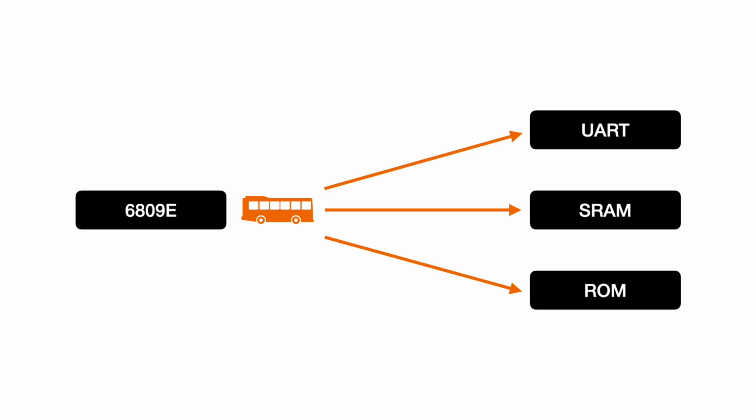Now, obviously, because I'm going to be building a circuit to match address bit patterns, I will need to decide how the address space on the system will be laid out so that I'll know what those patterns will be. The 6809 has a 64 kilobyte address space. In that address space, we have to put RAM, ROM, and the I/O devices. There's also some details that are specific to the 6809 that we need to pay attention to.